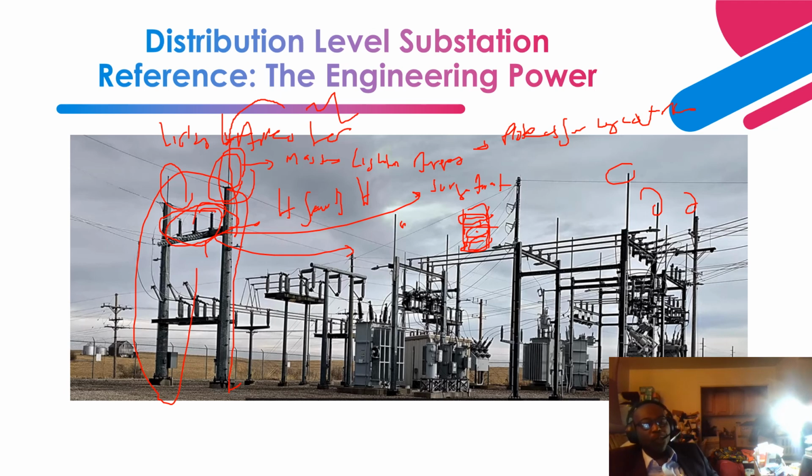Okay, so on this side are disconnect switches and your tubular bus arrangement. These are all connections with support insulators that protect the live tubular bus conductors from the ground plane. Then similarly, we have this arrangement. These are disconnect switches, as you can see over here, vertical breaker disconnect switches, before it gets to this power transformer.